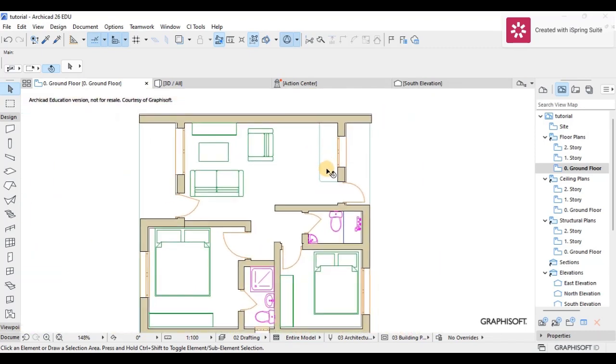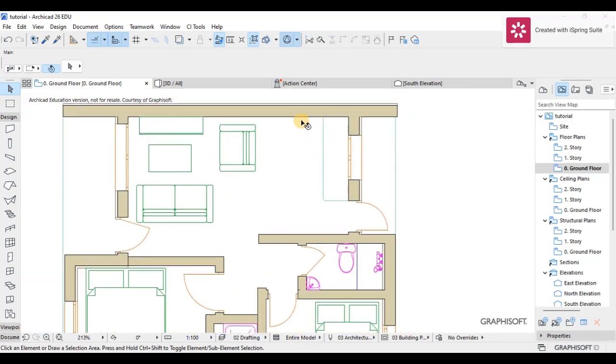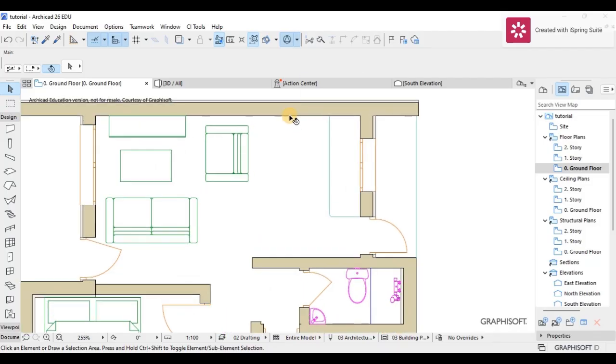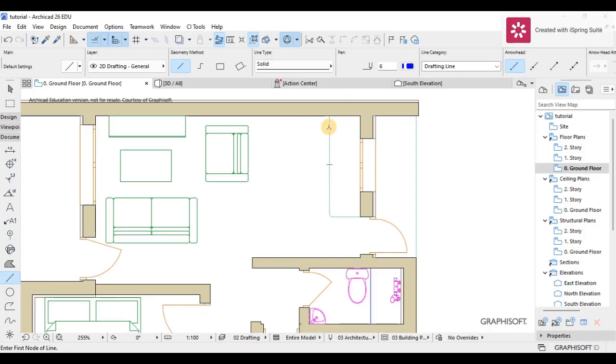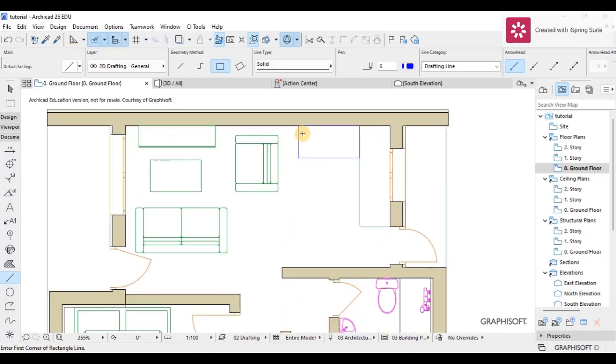The next thing we're going to do is place where I think our cooker is going to be, somewhere here. I'm going to show it out with my line tool, just to have a sense of how things are going to be. Let me make the width 600, go down and make it 600, and the top here 1200. Let me enter, and then we have that space for our cooker, maybe somewhere here.